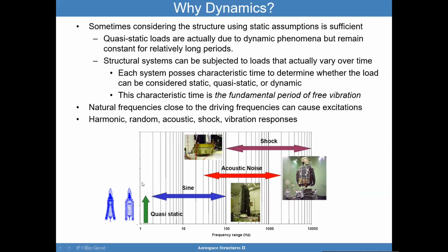So when I look at this plot here, this plot shows the frequency range at which we typically should be looking at stuff. When you're at a very low frequency range for a rocket, for example, you're looking at more of a quasi-static response, where the loading can be applied quasi-statically to the models. When you move up, you start to go into sine vibrations or harmonic vibrations. Then you have acoustic noise and then shock. And we'll be discussing some of this stuff later on.